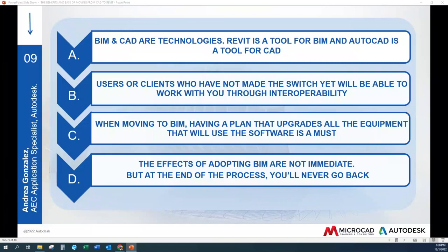They are commonly used together to incorporate designs created in AutoCAD within a Revit project. Firms may use AutoCAD on certain projects or components of a design and use Revit to generate BIM deliverables and to enable collaboration with other design disciplines. You can have a Revit project and send deliverables by exporting the Revit file in a DWG, and it will have a good behavior by transferring standards. You also can receive an architectural background in AutoCAD and link it to the Revit model for your guidance.